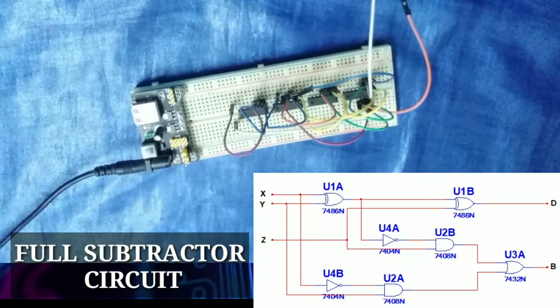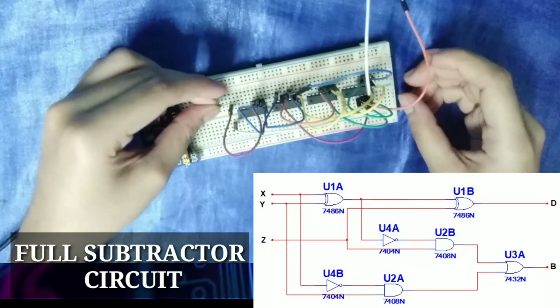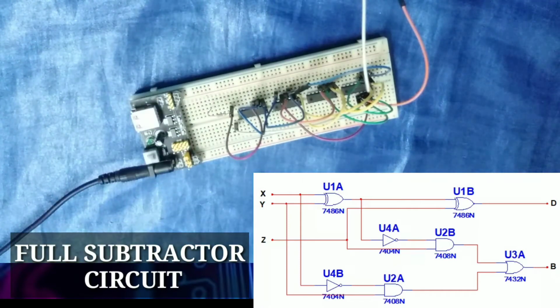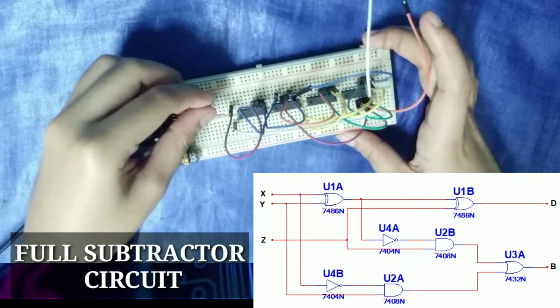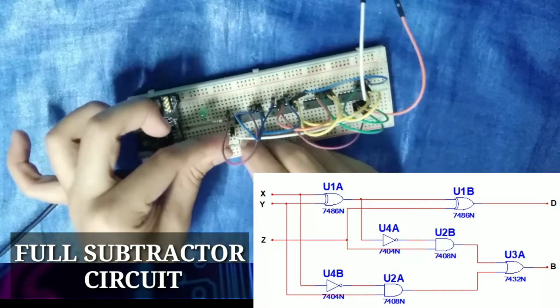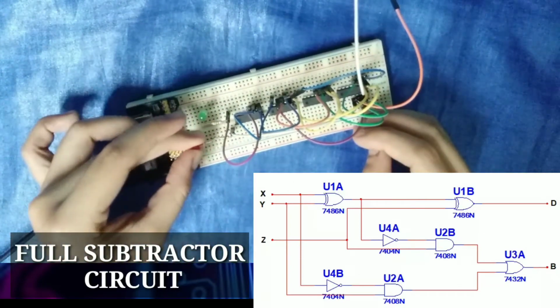And of course, do not forget our 360 ohm resistor connection and our LED. So our green LED will be for the B output, the borrow output, and our D output will be our red LED. Of course, do not forget our 360 ohm resistor. So here.